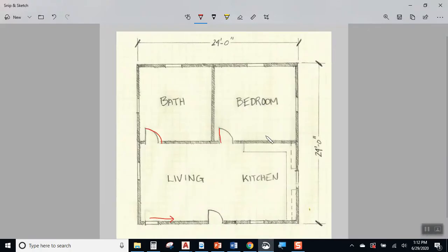Take a look at our sketch. What else are we working with? Well, we're working with a kitchen, and this line here represents the countertop. On a drawing that would show the entire building or the entire house if we're doing a residence, the detail level is not very high, so you wouldn't draw every single cabinet one after the other. You would draw the edge of the counter, and then the assumption is that there are cabinets underneath that countertop. And then another person might be asked to detail out the cabinets, but you're just giving them the overview of the entire building. So we just need to see the edge of the counter.